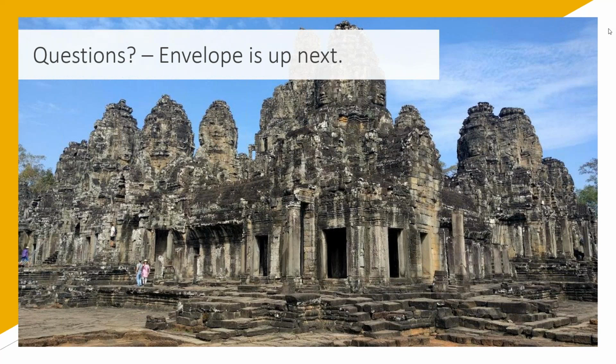The next question is for green buildings, designers require 19 watts per GPM for condenser water pumps. Is that the basis or conditions applied to it, or is it a generic requirement irrespective of size and application of building? This question is by Vikram Bansal. The way the standard is written right now is, if you have a water-cooled cooling system or heating system, if you have heat pumps, that is the maximum allowed if you're doing Appendix G modeling. So 19 watts per GPM is the maximum that you can have in the baseline. Your proposed design can be much larger than that if you want, but you need to make up the energy elsewhere.